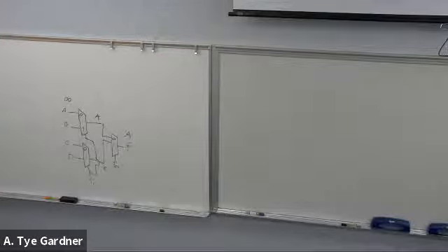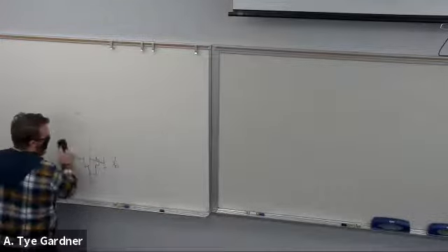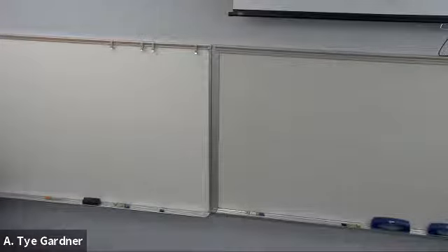Next device. There is a device that we call a decoder. Now, obviously, if I'm trying to decode something, there's something called an encoder, right? But almost every book ever deals with decoders first, so we'll stick with that. What a decoder does is it takes a binary input, usually, and outputs what we call a one-hot output.